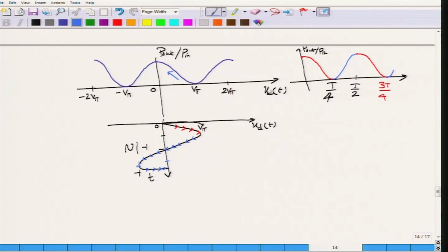Now what you can see here is that you have managed to obtain one pulse here, correct. You have managed to obtain one pulse here, okay, which lasts about T by 2 seconds. Why this would be T by 2 seconds? Well, you just do 3T by 4 minus T by 4, what you get is 2T by 4, which is equal to T by 2.